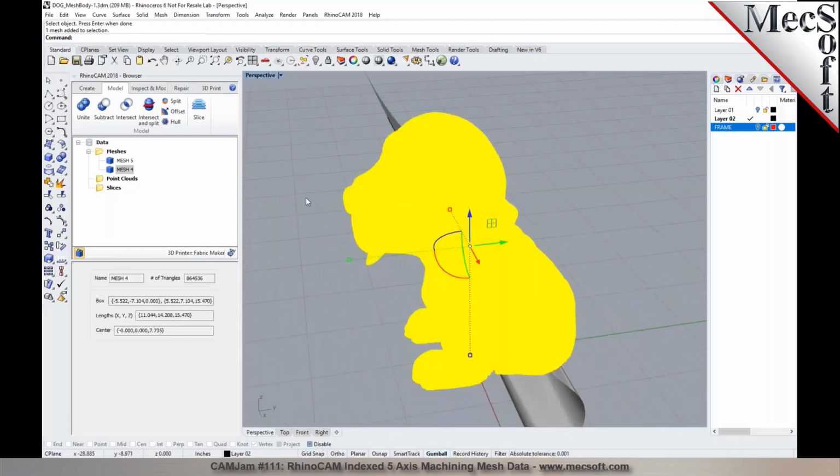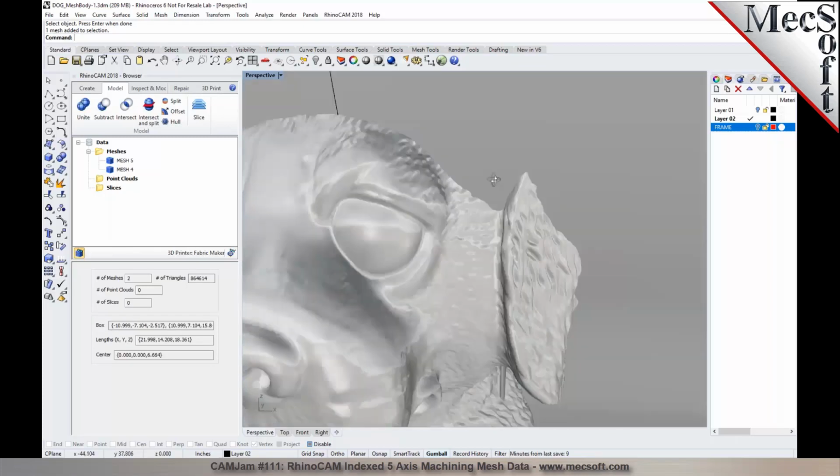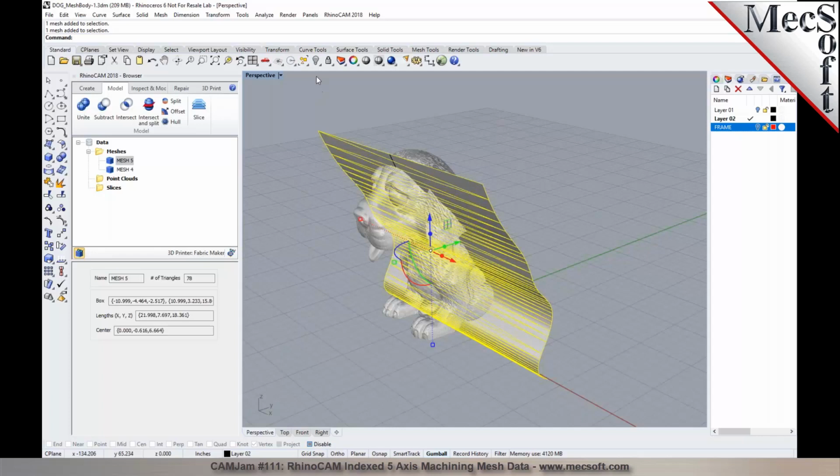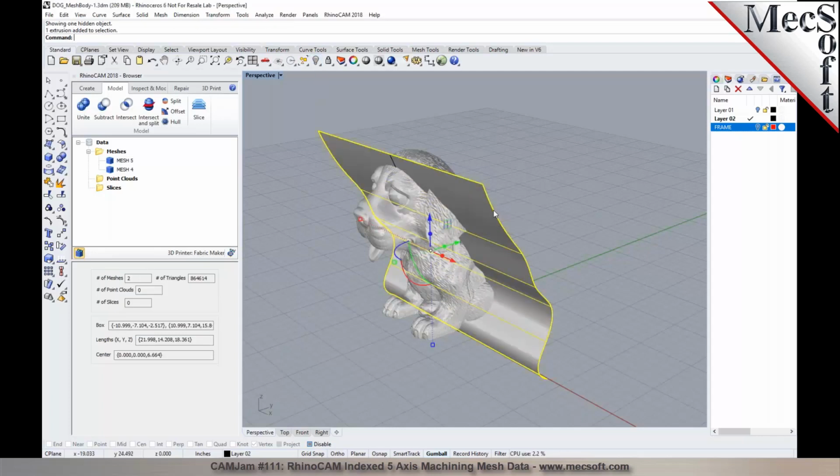Okay, so typically it should split it into two. I will have to look into it to see why this is not splitting in here. So I may have to check if I need to give it a wall thickness in here. So let me do that. Select this in here, and I can do an offset surface.